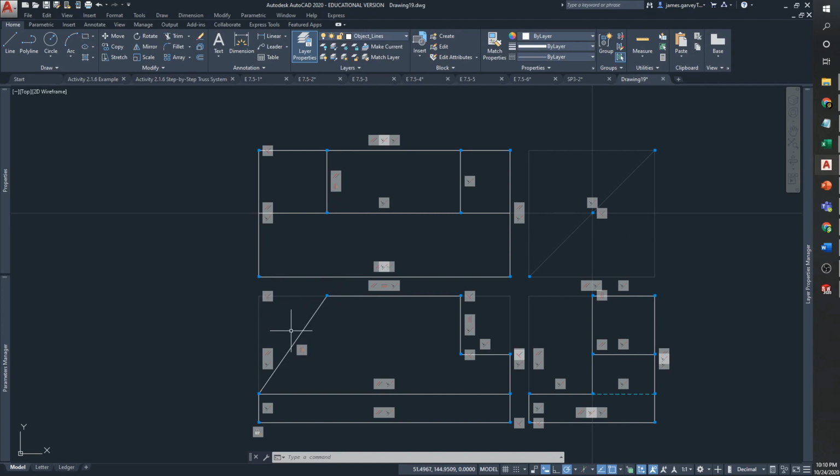All right, now I will add my dimensional constraints to this guy. I already have height, width, and depth on there, so now I just have to add in the details. Right click object, so I'm going to go line. Oh, sorry, that doesn't work. Oh, so point to point. Come on, there we go. 100. Hopefully that, yep, that moved that top line just the way I wanted it to.